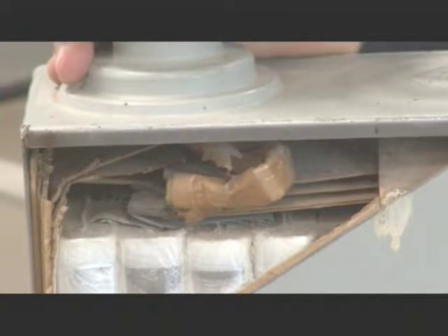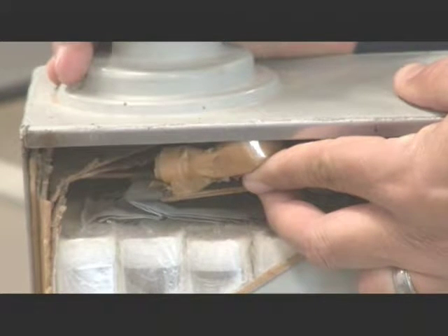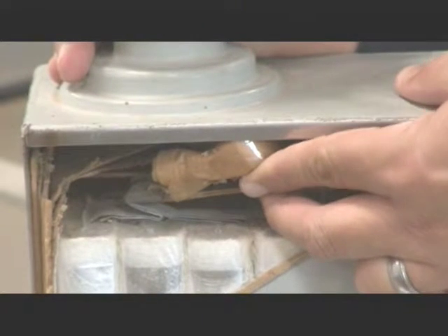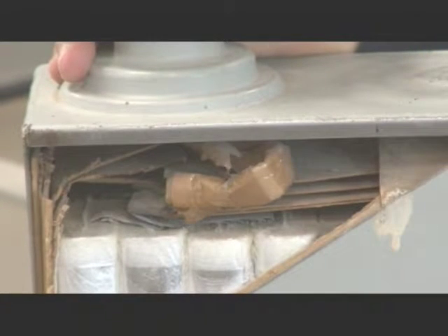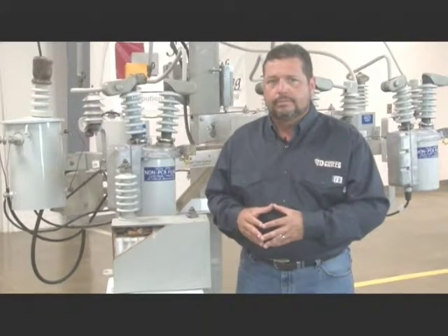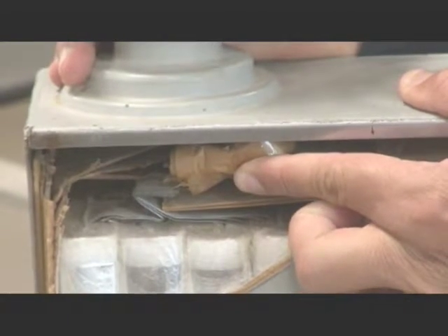The individual capacitor cells are connected together at the top so that the value of the whole capacitor unit equals the sum of all the cells. At the top of the cells, each set of plates is connected to the bushing, and the other side is connected to the grounding lug. The other internal parts include bleeder resistors that connect the two sets of plates together inside the tank.